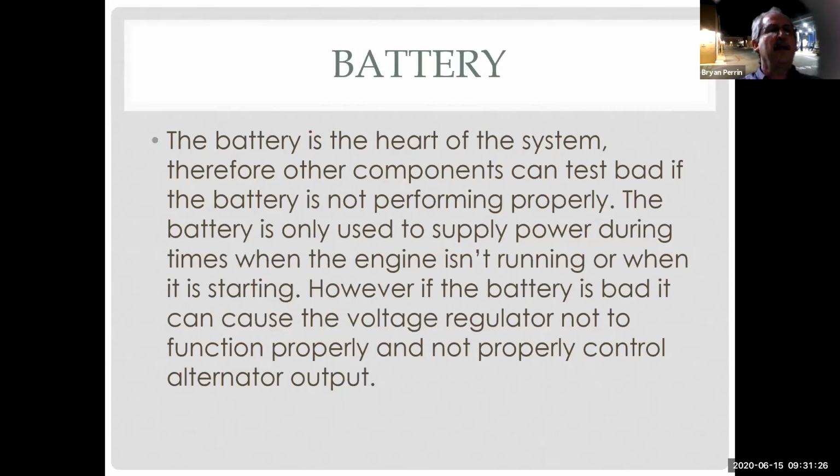On the other hand, my charging system, which runs my car as soon as I start it, won't work right if my battery's bad, because my charging system responds to what the battery wants. In other words, if the battery's bad and doesn't want a charge, my charging system will not charge it. If my battery's bad and wants too much of a charge or it's shorted, it'll actually overheat my charging system and damage it. So if my battery's not good, I need to take care of that first before I can test my starter or my charging system.